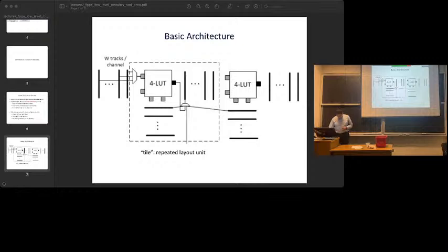You're saying this mux, should I also have it on these other inputs? No, if you want, you could use the mux to connect to the output. Sorry, the mux spec into this one? Yeah. You could use this to switch tracks between vertical and horizontal. Yeah, the LUT, basically all inputs of the LUT could be fed by the vertical channel if you want. You could. Yeah, I just drew it this way, right?